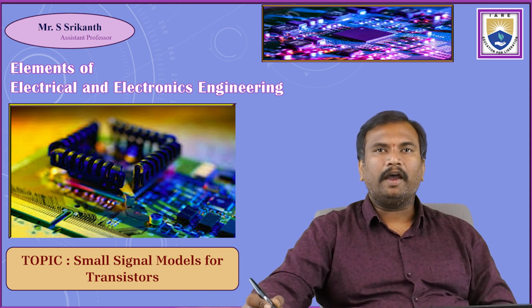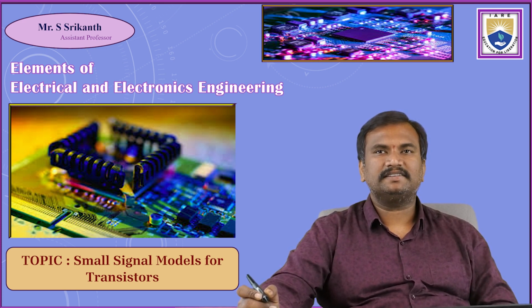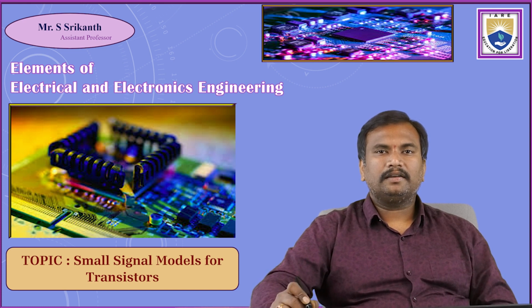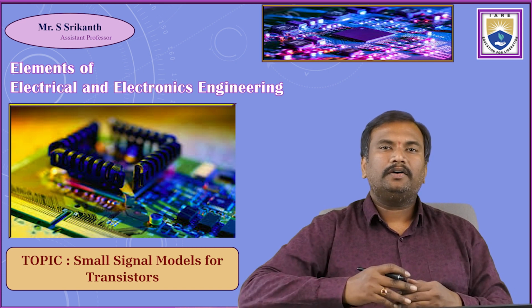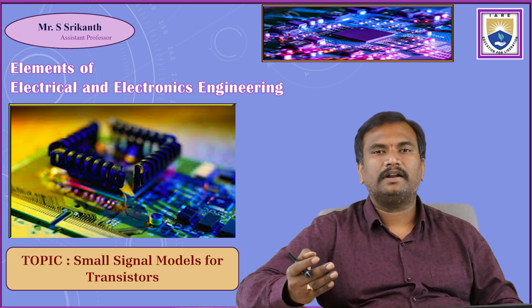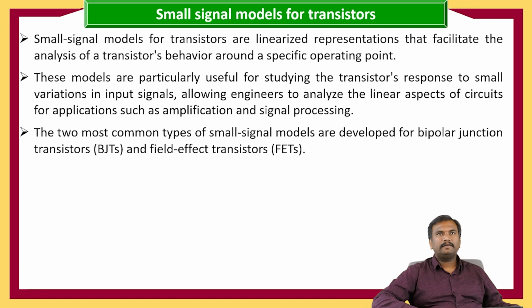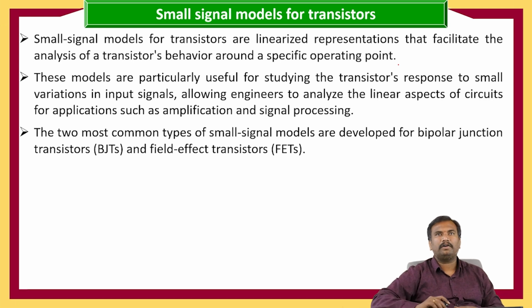In this session, I'm going to discuss the small signal models for transistors. We are going to discuss what a small signal model is and why we need the small signal model of the transistor. The small signal model is a linearized representation that facilitates the analysis of transistors' behavior around a specific operating point.